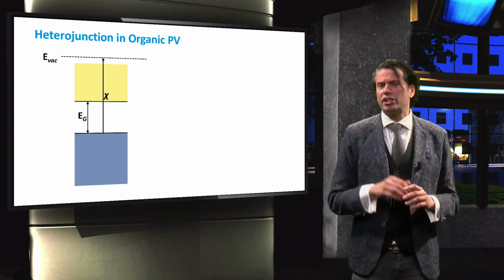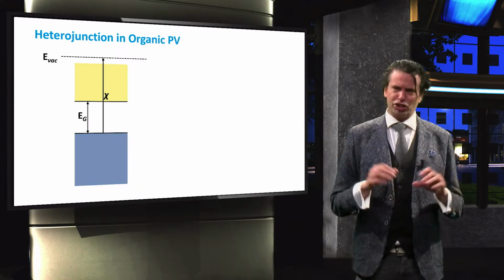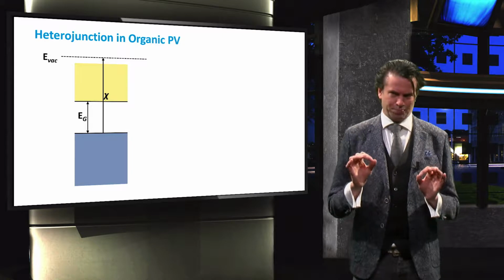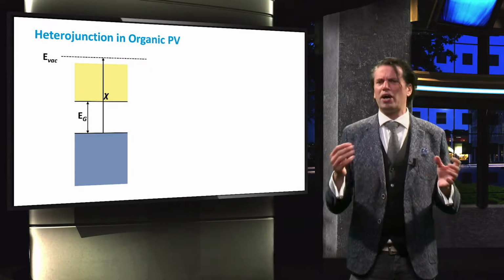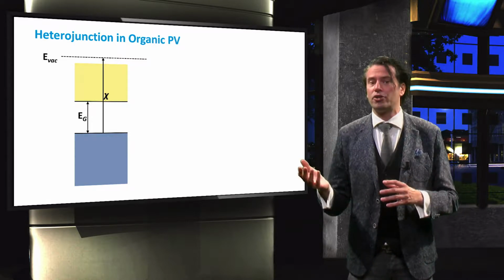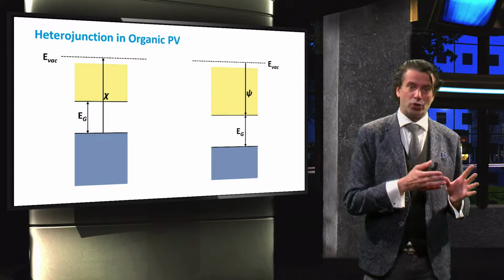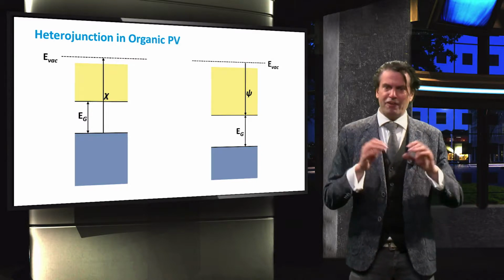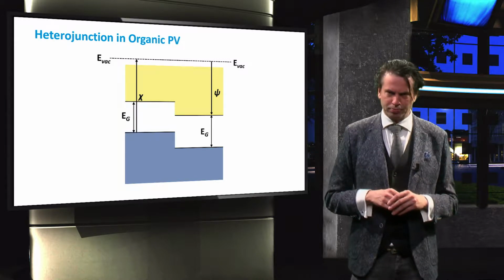By intelligently using intrinsic materials, we can still initiate charge separation of an exciton. Using the concept we discussed, we can theorize that by bringing together an electron donor on the left and an electron acceptor on the right, the interface formed will resemble that of a heterojunction.